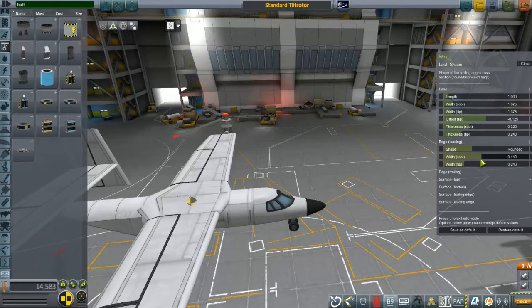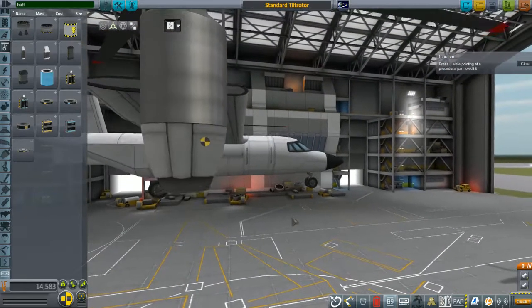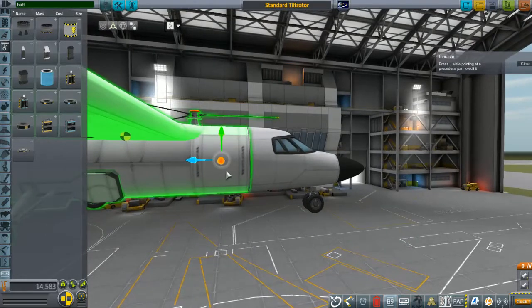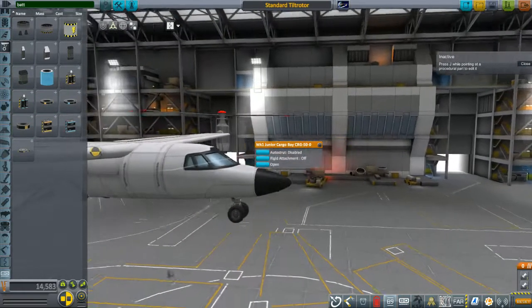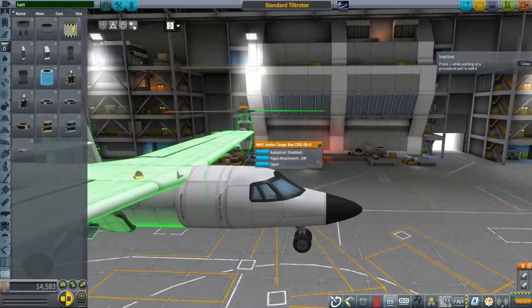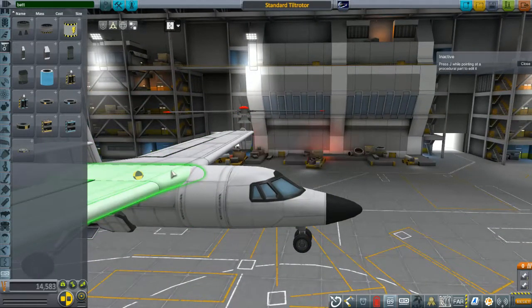Let's make it blur with that ring line on that body. That looks nice. Now, we just have one issue. How well does that look when it opens? Looks a little funky. But we're going to fix that here in a second by raising this assembly up slightly.